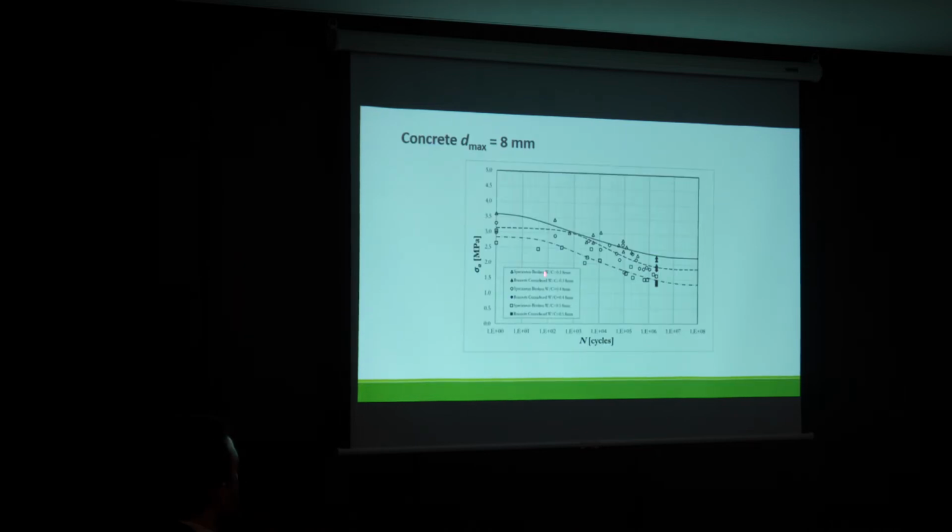Okay, now the important information about the fatigue properties. We measured the S-N curve, and you see immediately that, as we supposed, 0.5 has the lowest resistance, in the bottom part, and when we use a lower water ratio, the properties increase. And the index of dispersion is almost the same. It is nothing special, like some brittle material or something like this.